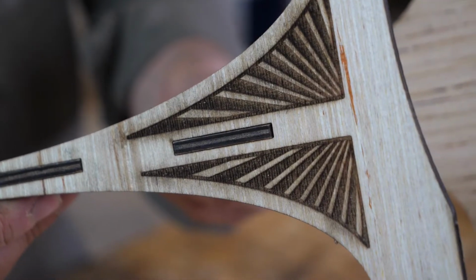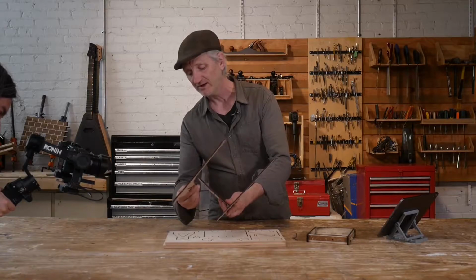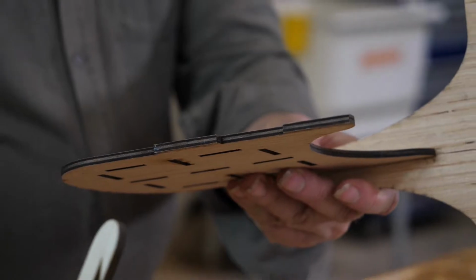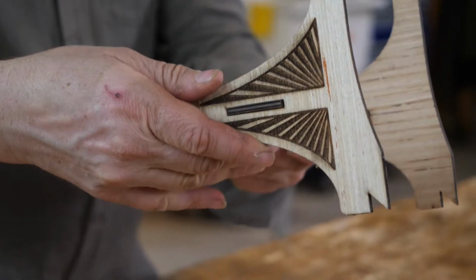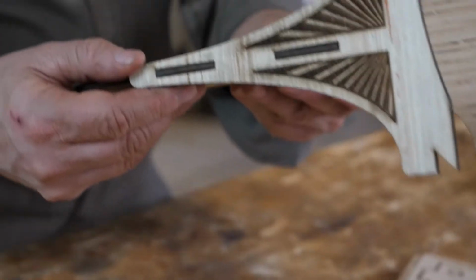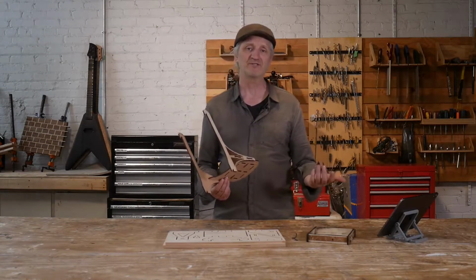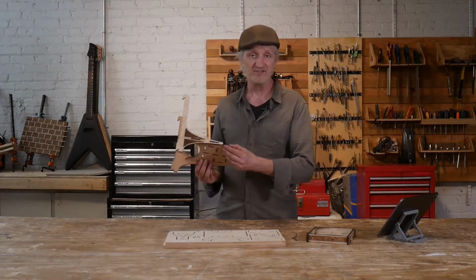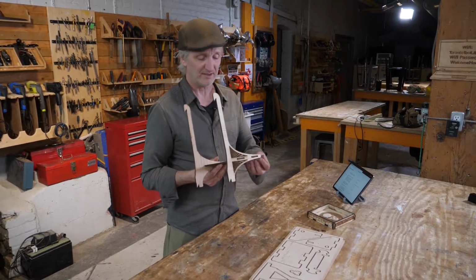Now, one of the problems that you can run into when you're doing this type of construction is that if your material is not a uniform thickness, you're going to run into problems with the fit when you attempt to assemble it with your slots. This one is pretty good, but it's a very common problem because even if you go to the store and you go to the exact same aisle in the exact same place and you purchase the same material twice, there's no guarantee that it's going to be exactly the same thickness.